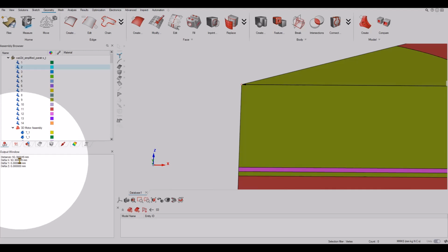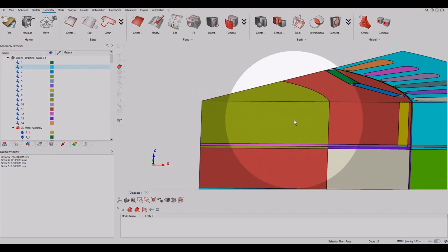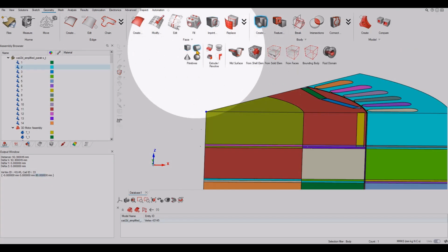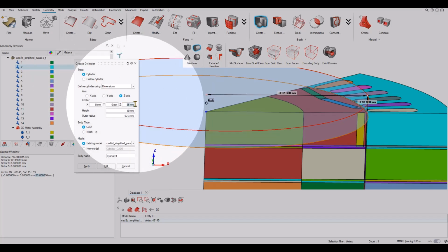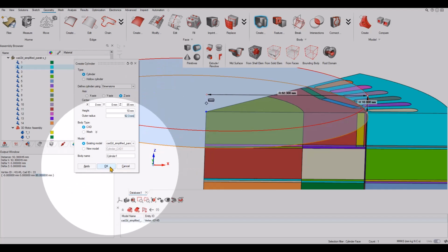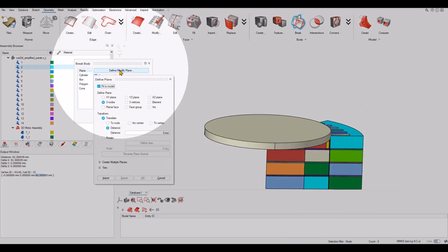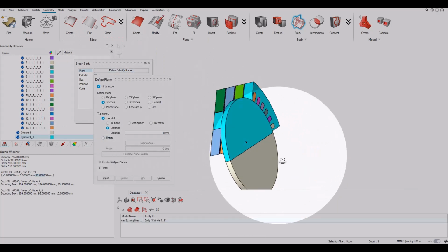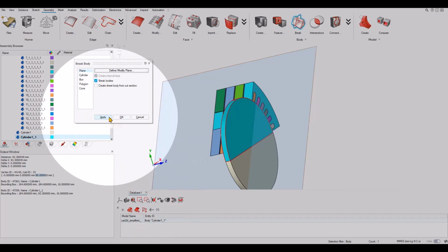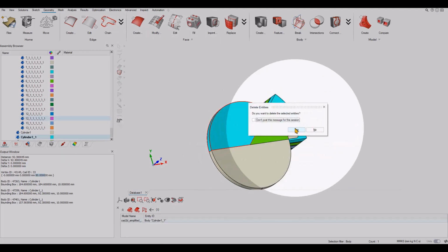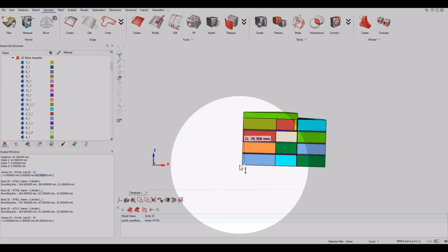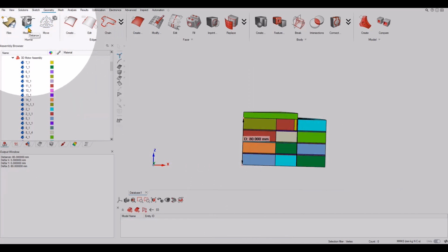I want now to complete my sliding cylinder. So I need a layer of air on the top and a layer of air on the bottom. That's why I am creating this cylinder, and this cylinder I will first cut to conserve only one portion. So I make the cut according to the XZ plane and according to the other periodicity plane. Good, that's it.